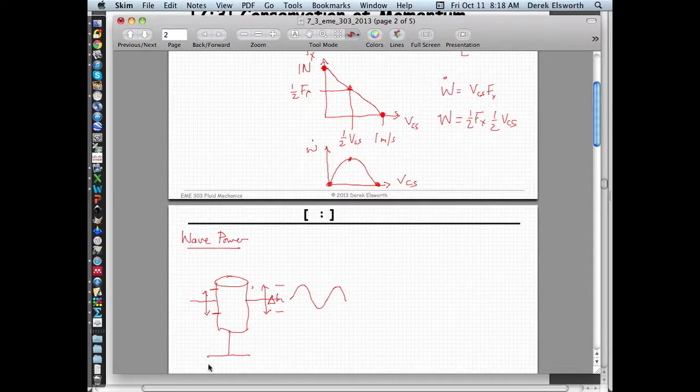And so those two end members, you're at these 2 points. So I guess what you need is to be able to attach it to the floor so there's some actual give in this. This isn't a resistor. It's a mechanical resistor. It could be an armature, I guess, of an electric motor for that matter. And you'd be able to use this in some useful way. So in other words, the buoyant force that you'd have acting as this goes up, if you can remember, is unit weight of water times the volume displaced, which is going to be unit weight of water times the cross-sectional area times delta H.